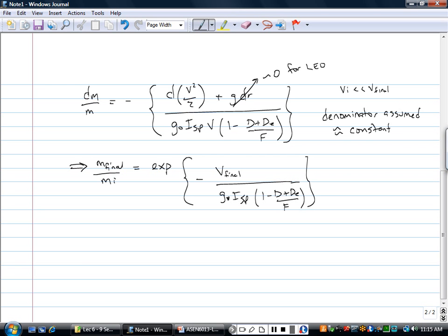The system then makes a little bit more sense. Now, same as before, we need to get that velocity in terms of our energies, and we did this one before, so I'm not going to repeat it, other than give you the details where we have our other force term, mg cos theta minus L. For this case, lift is going to 0, cos theta is going to 1, small angle, v squared equals gr. Get rid of the m's, yeah, we're good. Which equals g naught r naught over r.